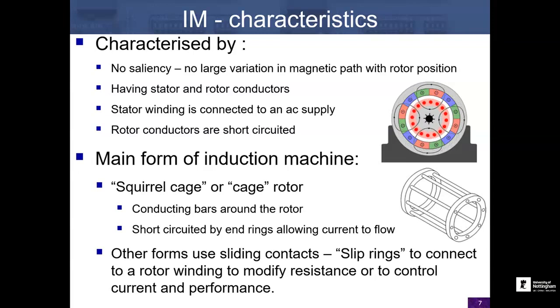You can see the flux lines linking the stator and the rotor, and you can just about notice that actually that rotor is moving slower than the stator. So for the fundamental principle of operation, if that rotor is moving at any speed other than the same speed as the stator field, it's going to see a change in the magnetic flux.